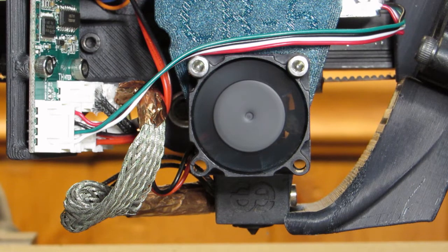And even if you're not working with a direct drive machine, where the direct drive has got a grip on the filament, if I pull the filament I can't help but pull on the extruder, it's going to influence things. If I have a Bowden tube there and a filament pushed in, if the filament has any stiction whatsoever, if it's touching the cold zone or the hot zone and it's gluey and in pulling on it there's resistance, that resistance will translate into an upward force on the nozzle. So pulling on the filament will influence where homing thinks is bed 0.